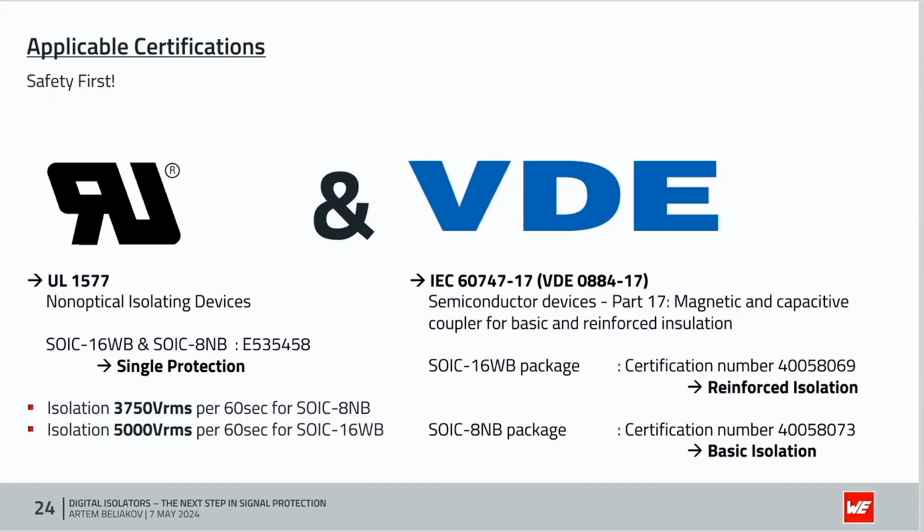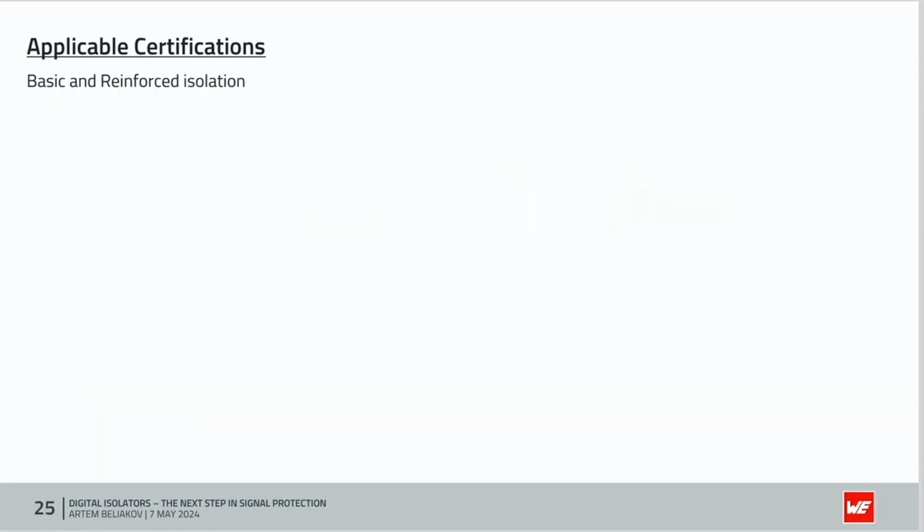According to this standard, our digital isolators in the SOIC 16 widebody package provide reinforced isolation, and digital isolators in the SOIC 8 narrow-body package provide basic isolation. What the difference is between basic and reinforced isolation I will explain on the next slide.